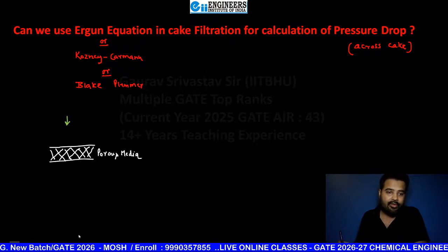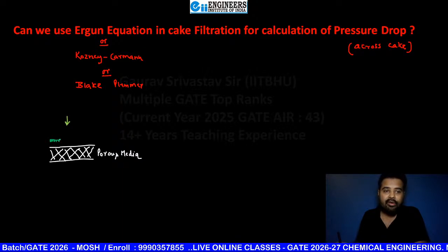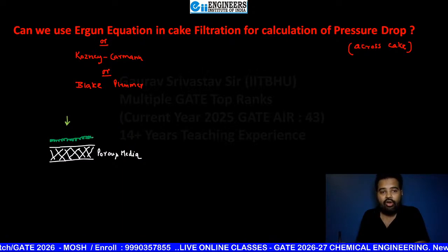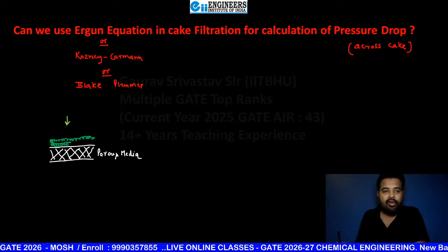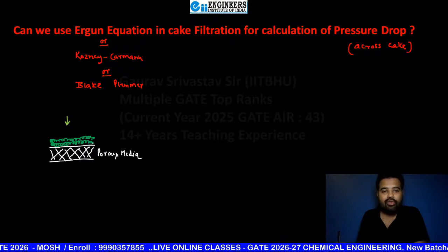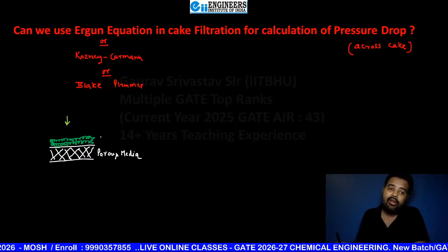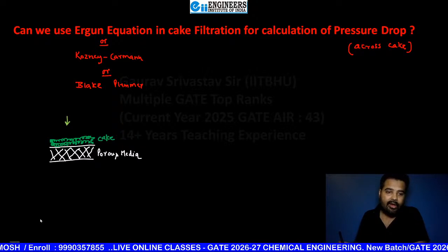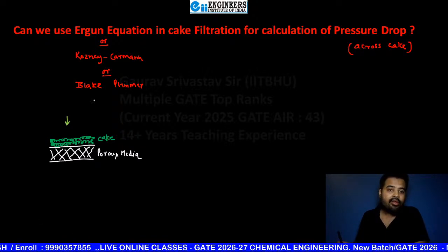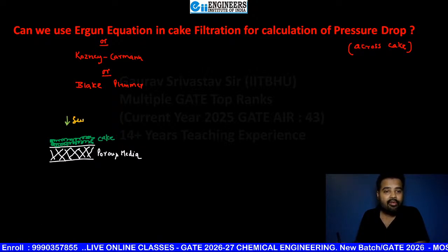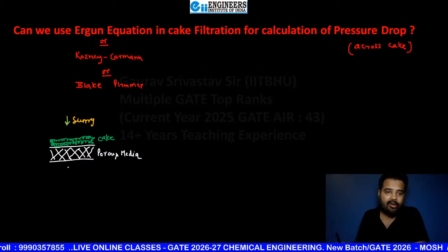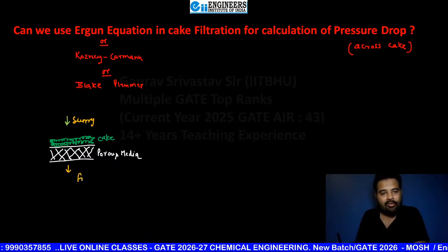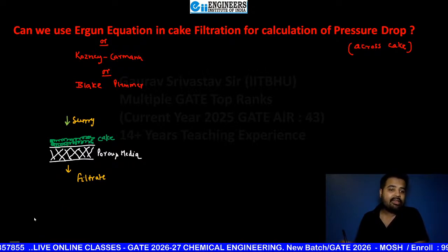and if from the bottom you will get filtrate, definitely, but the solids present in your filtrate are going to accumulate on the surface of the porous media as a cake. Now what is happening here? The slurry that you fed here, from the bottom you are getting filtrate. So what I'm asking here, my dear students,